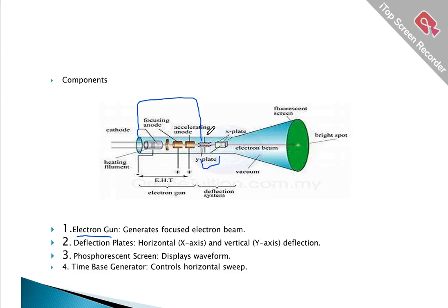Here we have two regions of electric field and magnetic field. Electric field bends the electron beam in horizontal direction on the screen. It will bend just like this, but magnetic field deviates the electron beam in vertical direction. In this way, when electron beam strikes the screen of the TV, it will produce shining on the whole screen. Then we can see the picture of the audio signal which is broadcast by television companies.